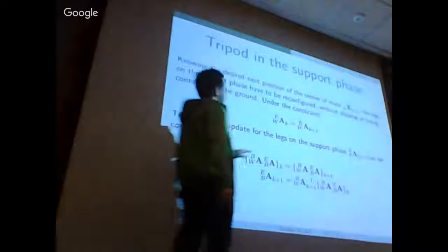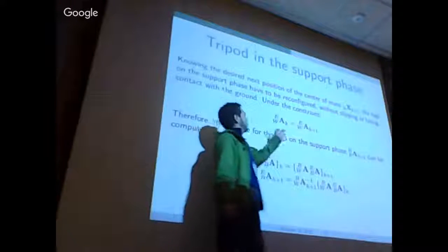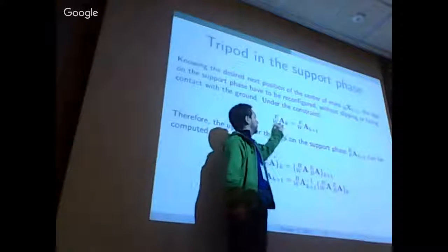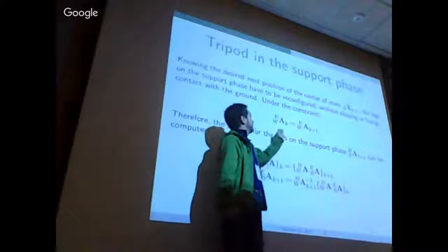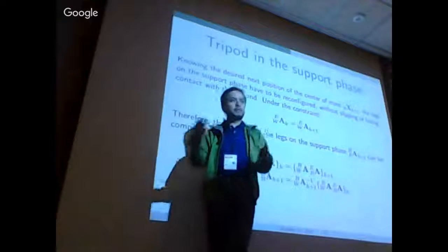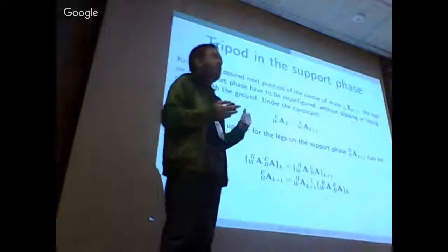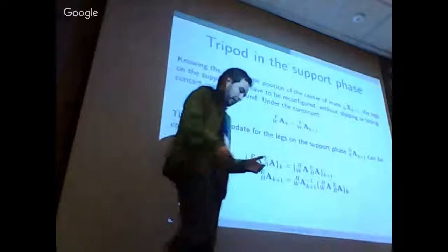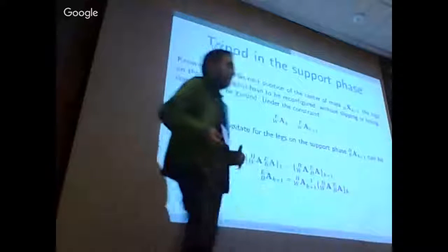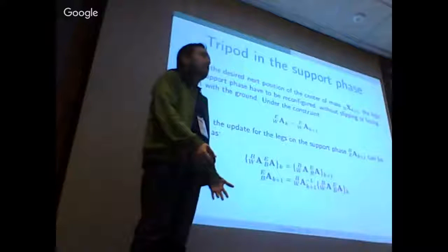As an example, here I show you a rigid body transformation. What this means is that with respect to the world reference frame, the rigid body transformation from the tripod supporting the body of the vehicle has to remain equal. That means that when I propel the center of mass of the robot, the support tripod remains fixed to the world reference frame.